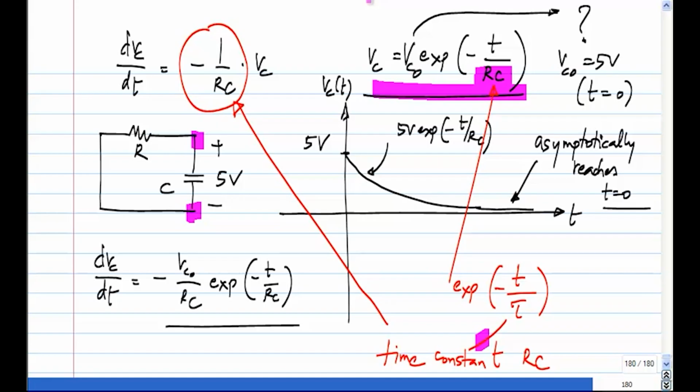After all, what is happening? Initially you have some charge across the capacitor that is leaking through this R, and then goes all the way to 0. Now if the resistance is very large, then it means that very little charge is taken out per unit time, so it discharges very slowly. Alternatively, the time constant can be very large by the capacitor being very large. So that means that it has so much charge that if you take a certain amount of current out of it, the reduction in voltage is much smaller. So these are all just intuitive explanations for what comes out algebraically very easily. And it's also quite important to realize these things intuitively.